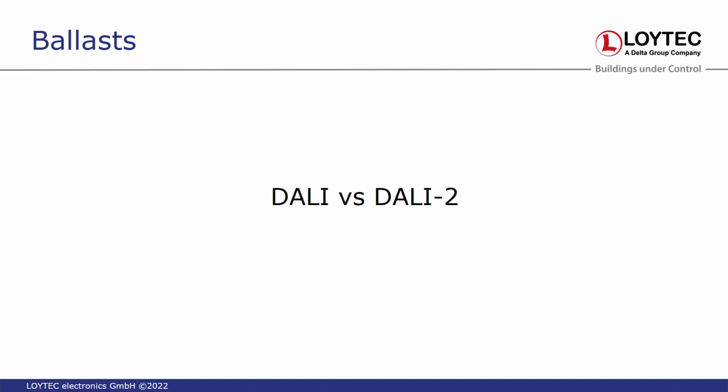And you are right that when you are only DALI 1, this doesn't mean that it doesn't work with a DALI 2 device, or that for sure there will be issues, but there is the possibility that there are issues, because there are also more restrictive timing definitions in the DALI 2 standard than in the DALI 1 standard.